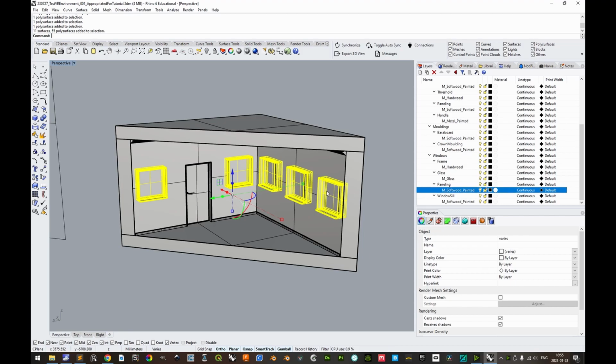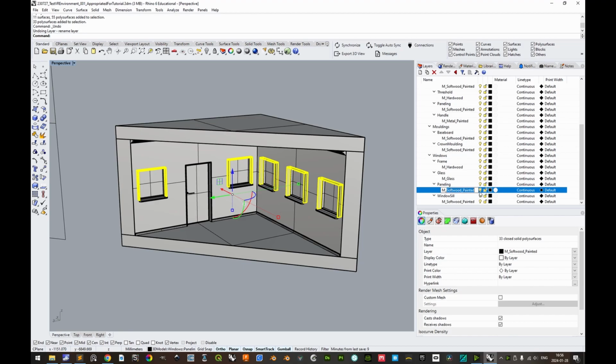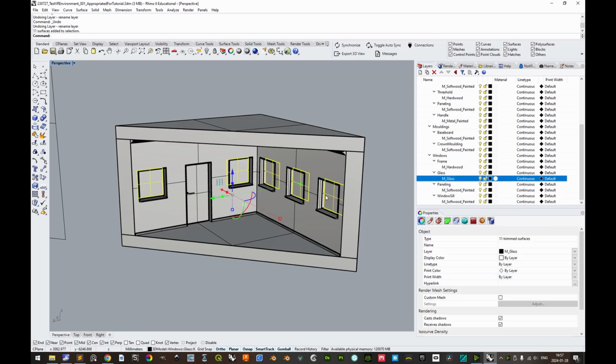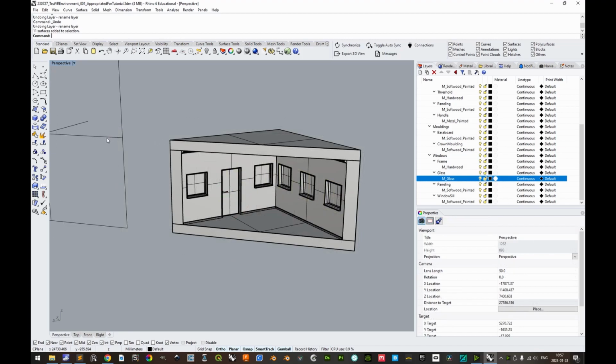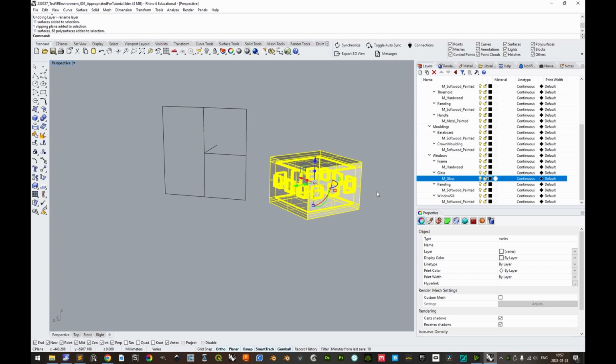And if you want to change the intended material slot for any type of element, you can just rename that specific sublayer. All unique layer names will be separate material slots in Blender. So if you have multiple, they will be treated as one in Blender. For any glass panes, it is recommended to only have a single surface per window opening to make it easier to render in Blender. Let's disable this clipping pane and select every Brep object that we have here.